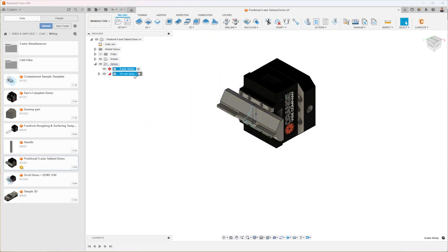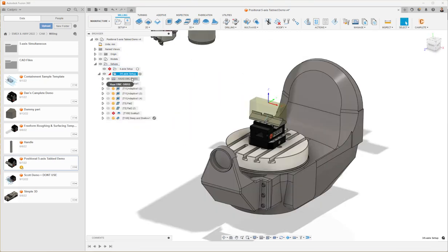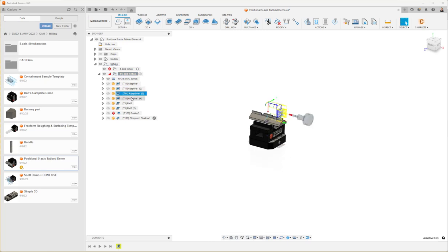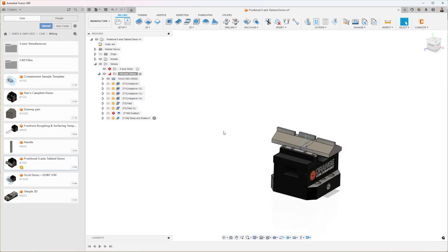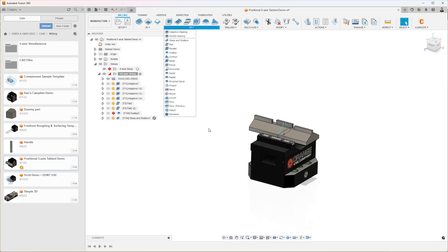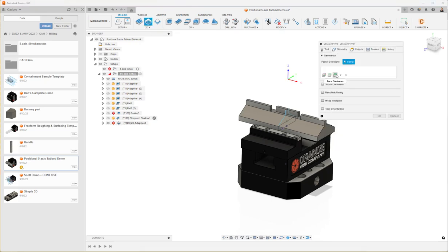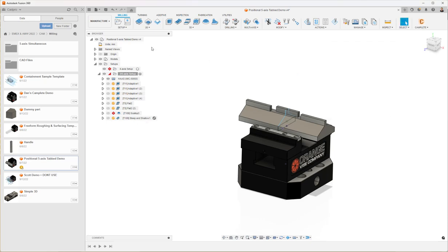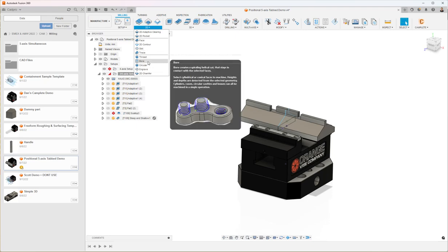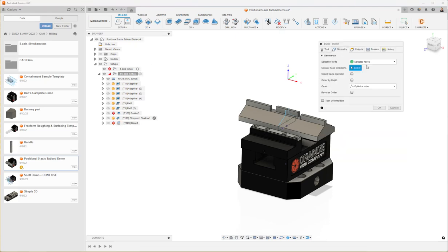and the 3 to 5-axis setup is already pre-toolpathed with a whole bunch of adaptive toolpaths and flats, and the more of the 3D toolpaths you use, the more dependent they are on the model. But increasingly with 2D toolpaths, so like 2D adaptive clearing, you can do pocket recognition, and then with holes you can find holes based on boring, find them based on diameter range along the tool axis, and so on and so forth.